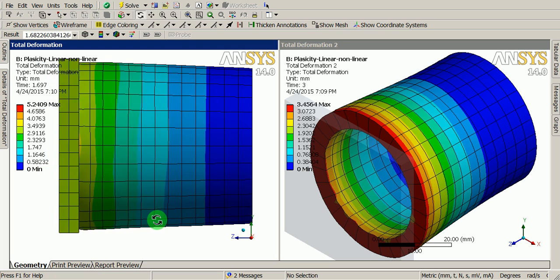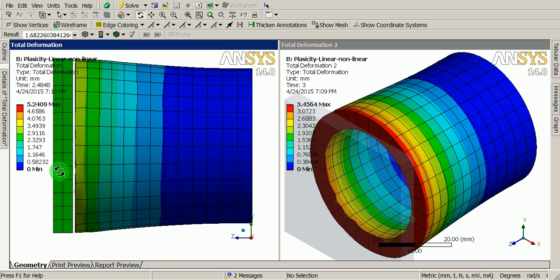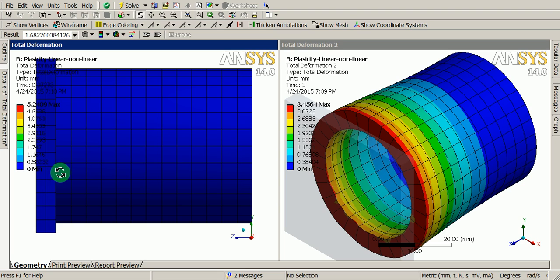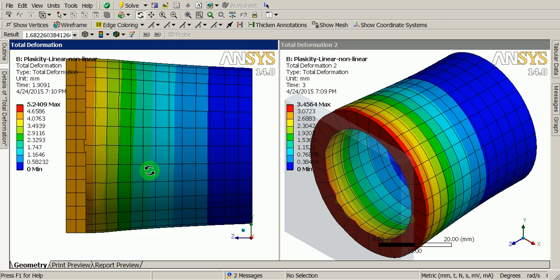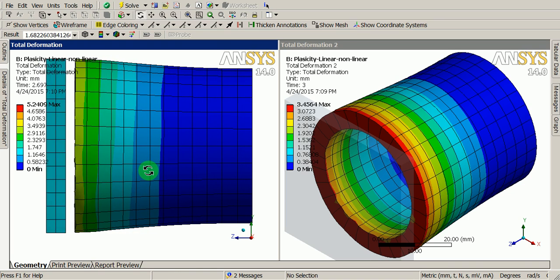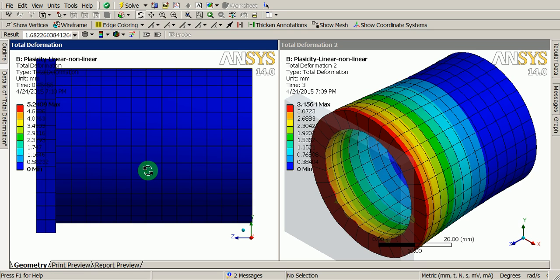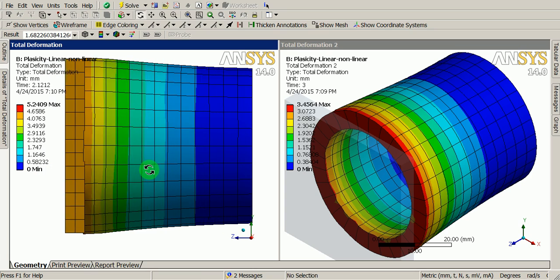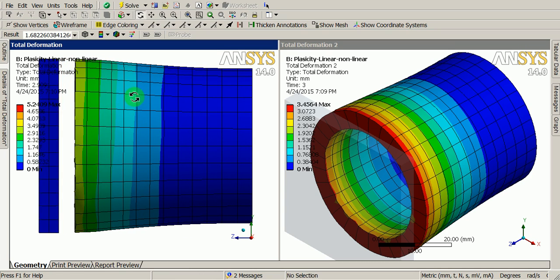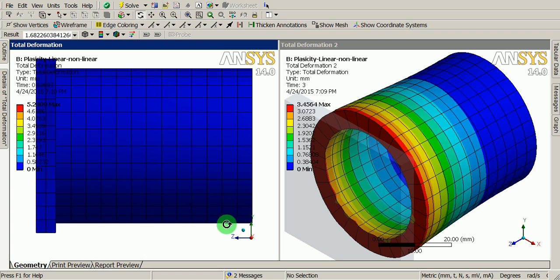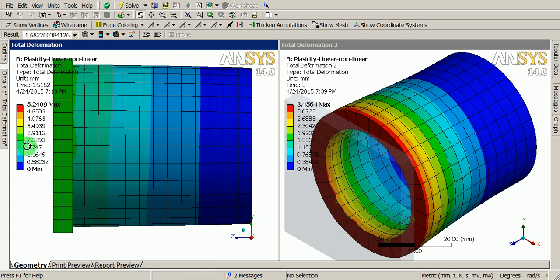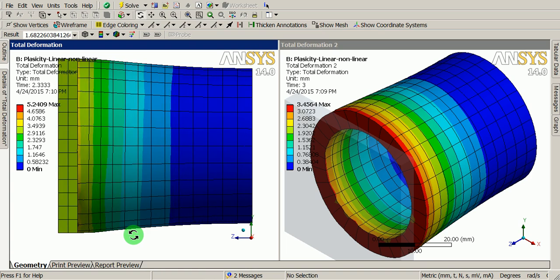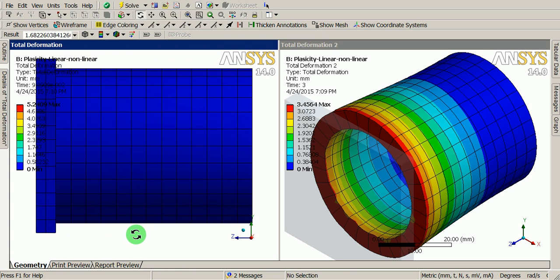When we observe carefully, the platen is going to displace the bush for a distance of 5 millimeters and it is retrieved back. But the bush is going to retain the deformed state itself and fail to regain its original shape, size and dimension. This behavior is due to its nonlinear material properties.